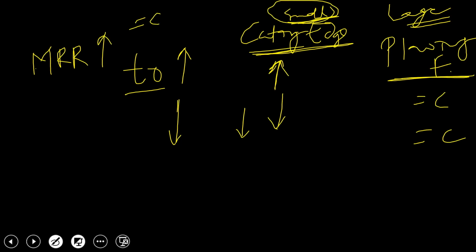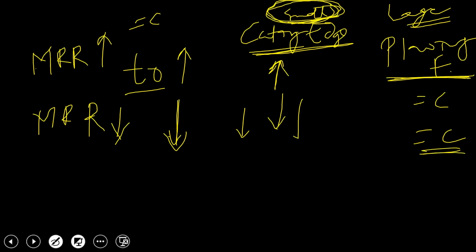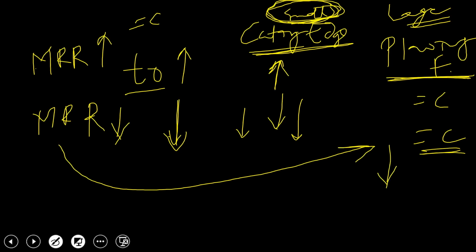But when you decrease this t0, the material removal rate is going to decrease drastically, but this plowing force component is constant, and this small component of force acting on the cutting edge will decrease. But if you compare the decrease in material removal rate with total force, the total force will not decrease considerably.